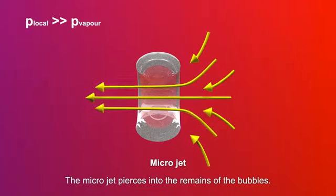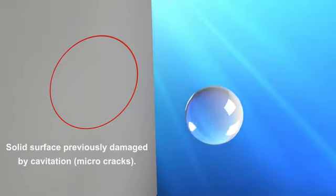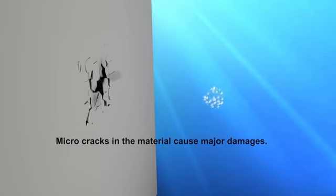The bubble becomes a torus and disintegrates further. The microjet continues to flow in the liquid and can hit a wall. Through its concentrated impact, even high-strength material can be damaged. The implosion releases energy in a very short time concentrated in a very small spot. If the microjet hits a surface, it damages the material by a localized short-term overstraining. The material starts to evolve microcracks, and later material can break off.